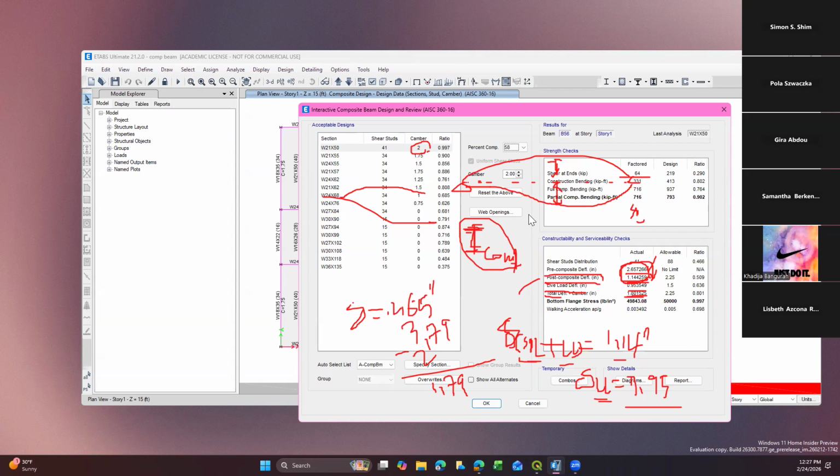So here 1.8 versus the total deflection criteria. Deflection due to the dead plus live load we try to keep less than L over 240. Live load deflection is L over 360, but for total deflection our criteria is L over 240. So you could calculate 45 times 12 divided by 240, so 2.25, right? So this is the actual service deflection check.